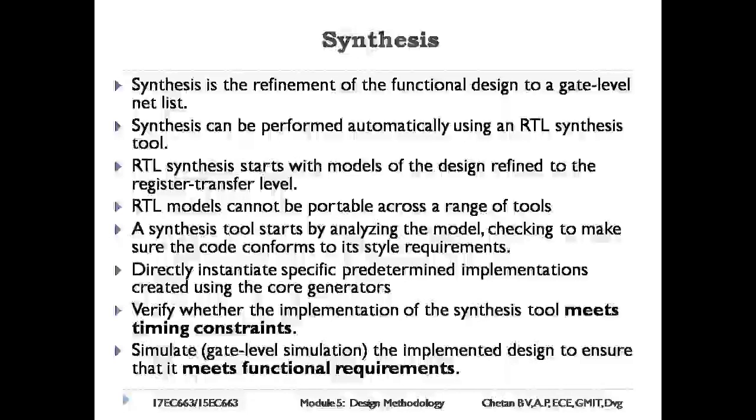This involves things like analyzing wire and variable declarations to determine the encoding and the number of bits required to represent the data, analyzing the expressions and assignments to identify combinational circuit elements such as adders and multiplexers, and to identify the input, output, and intermediate signal connections, analyzing always blocks to identify the clock and control signals, and to select the appropriate kinds of flip-flops and registers to use.